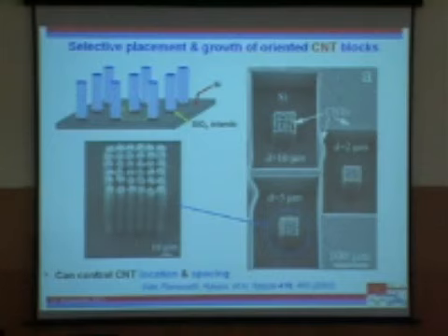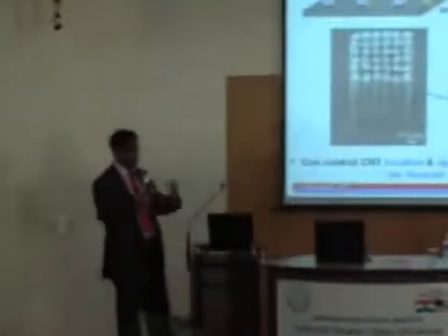So this is pretty good. That means we can assemble bundles of carbon nanotubes. Good first step. And these are all unidirectional structures. These can actually be done by other methods also. For example, put down a catalyst, pattern it, and then do the growth. But here the beauty is, you just put the silica discs, and the catalyst and the precursor, everything comes from the gas phase. So all the design comes before the actual growth occurs.